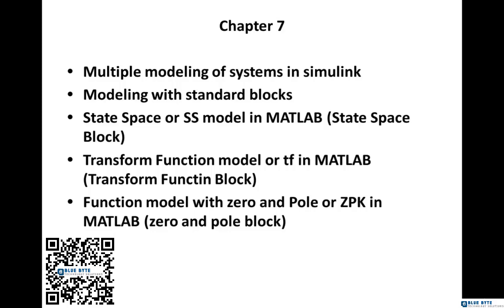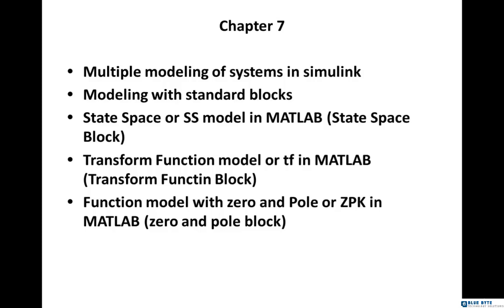The next method is state space or ABCD matrices. I will explain it in the next slide. The state space equals SS code in MATLAB. Then we have the transfer function model or TF in MATLAB, the transfer function block, and the model with zero and pole, or ZPK in MATLAB, or the zero and pole block.